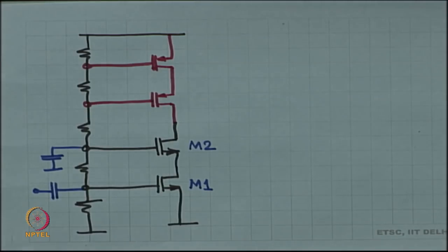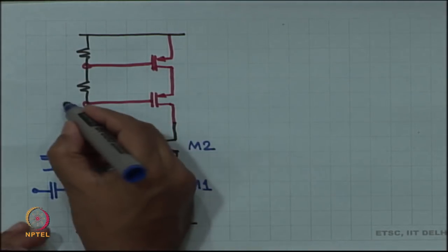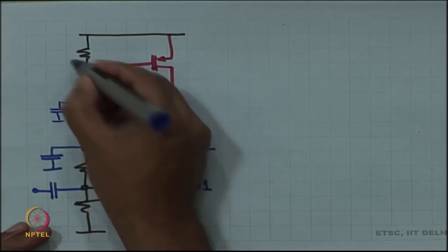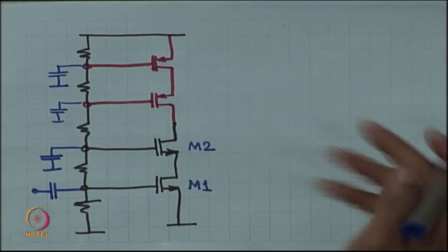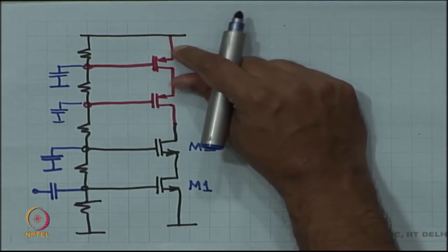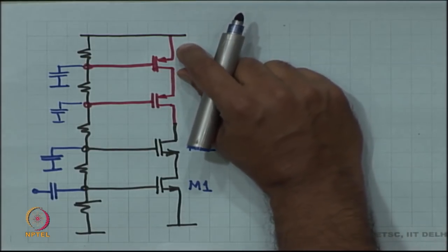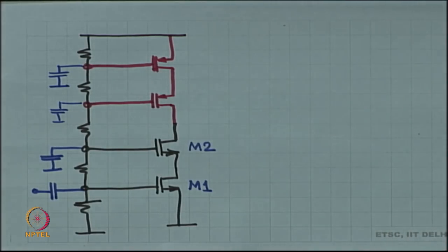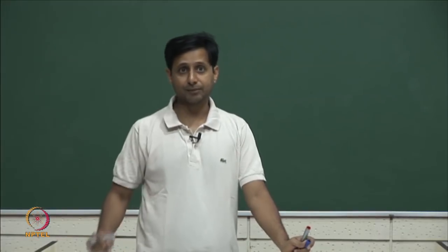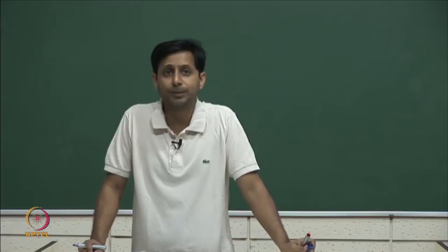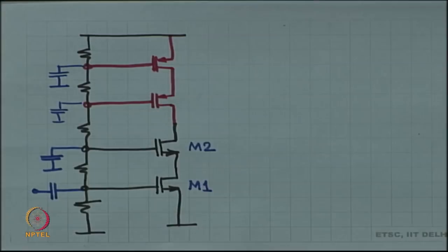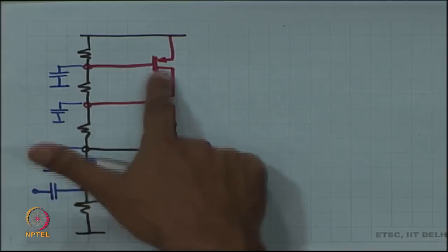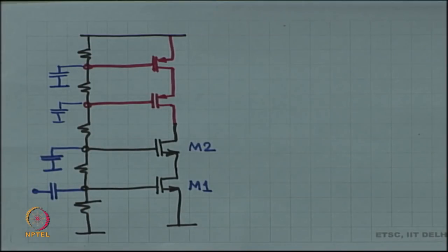Okay. Once again, common gate, and the top one is nothing but just an RDS. The top one is not even a MOSFET. I mean, effectively all it is doing is it is providing the required RDS. No, it is actually a better idea to have a MOSFET over there, not a resistor, right. So, do not place a resistor. Yeah, MOSFET is what it is. Okay. So, this is the structure that we had, and these resistors give the required voltages at the gates of these individual devices.